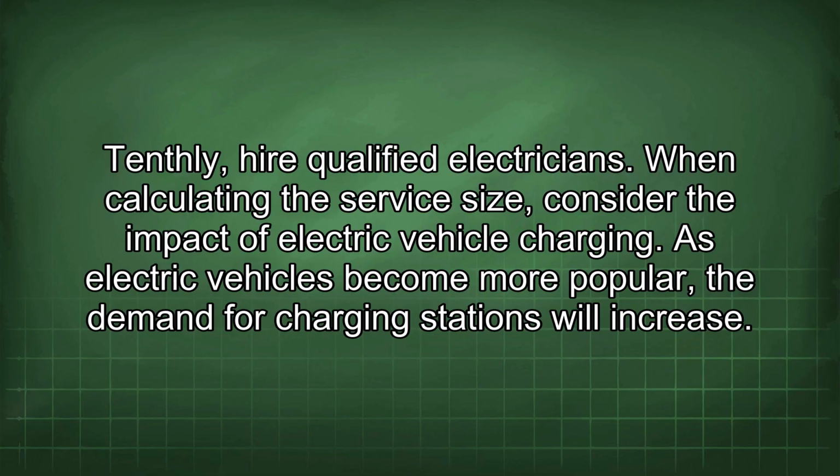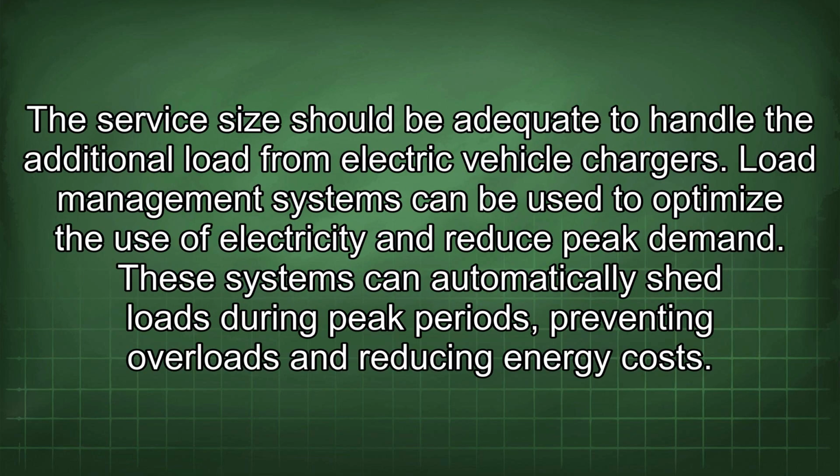As electric vehicles become more popular, the demand for charging stations will increase. The service size should be adequate to handle the additional load from electric vehicle chargers. Load management systems can be used to optimize the use of electricity and reduce peak demand. These systems can automatically shed loads during peak periods, preventing overloads and reducing energy costs.